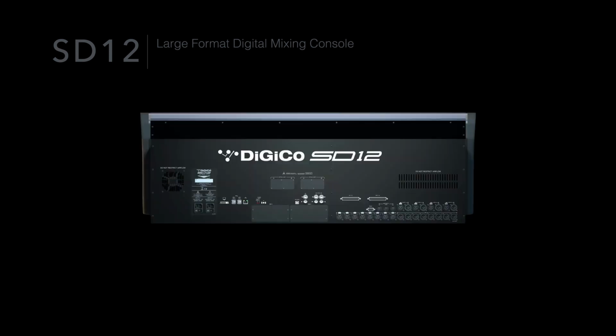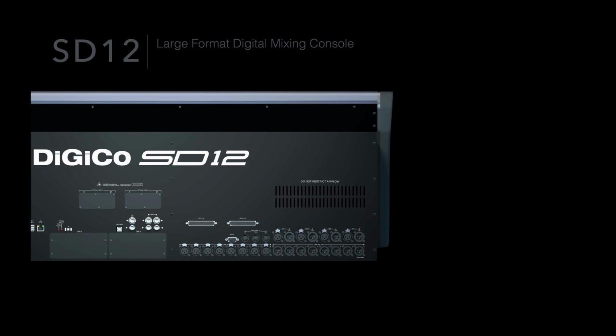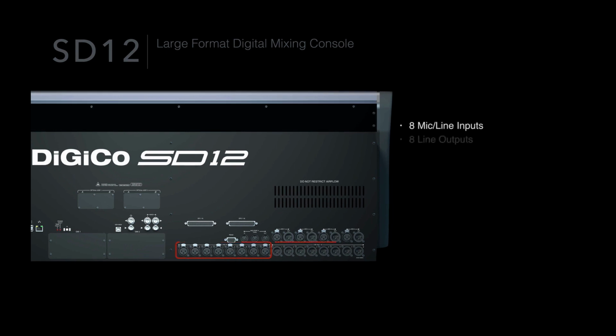All right, let's take a look at the back of the console as before to show you how audio gets in and out from here. First things first, we have our 8 mic line inputs, 8 analog line outputs, and 8 channels of AES in and out over 4 pairs in and 4 pairs out of AES. We also have 2 MADI ports. Each of these MADI ports are 64 by 64 channels at 48K, and we have 2 of them, which you're going to see. We're going to use these in a minute to connect to our stage racks.